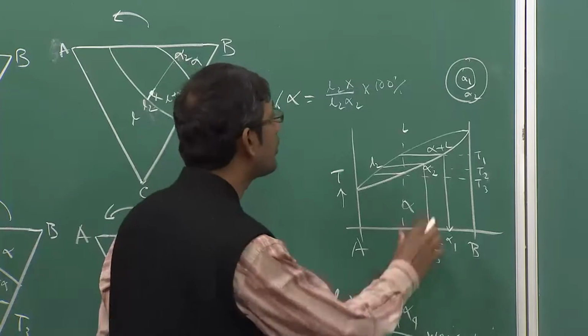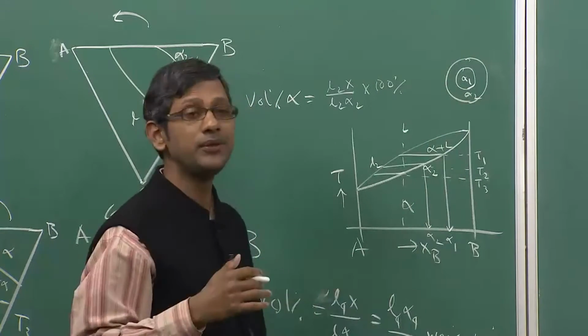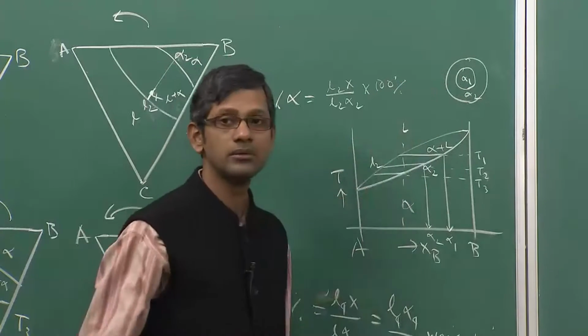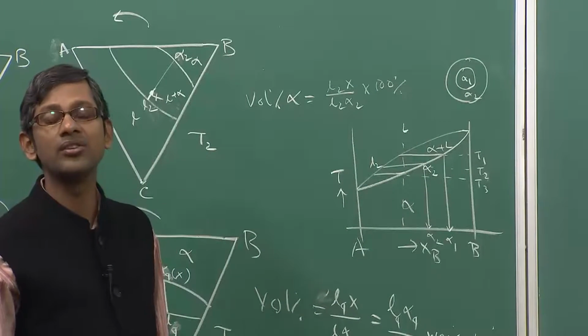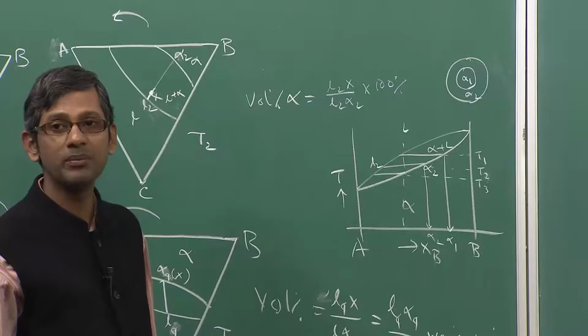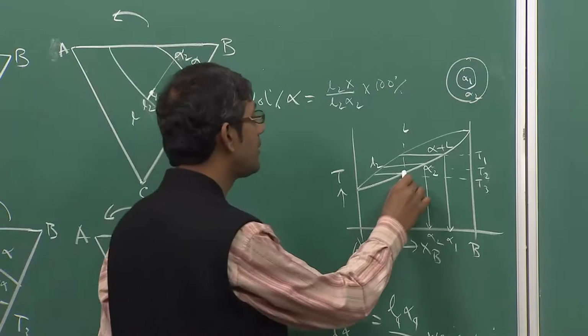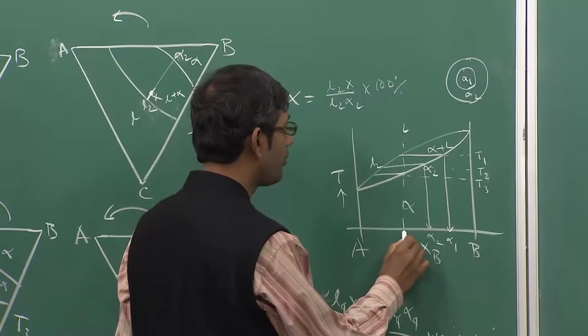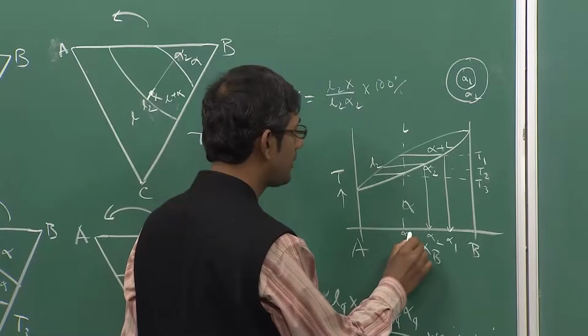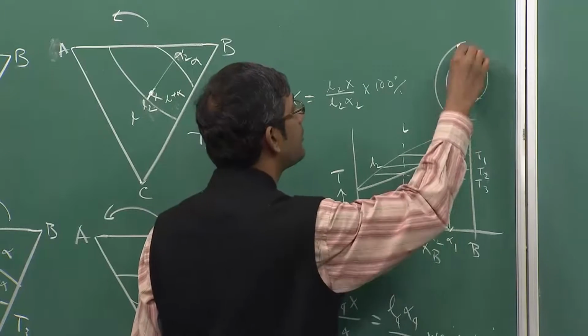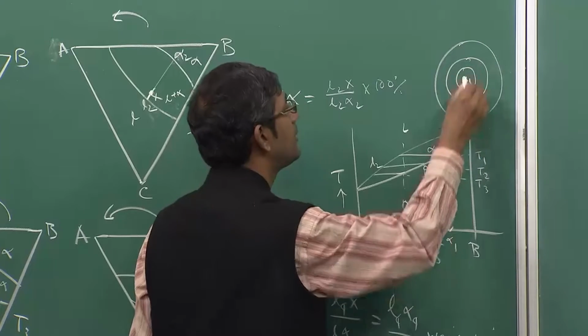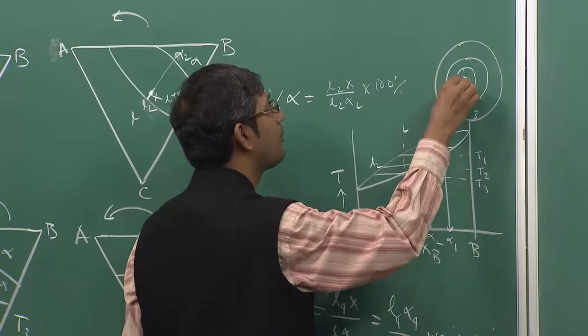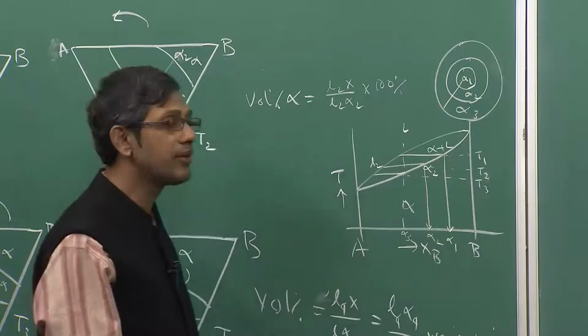Therefore, in order to homogenize them, B has to diffuse from alpha 1 to alpha 2, and this diffusion in solid is not allowed because of the non-equilibrium nature of the processing. So, obviously, the last solid which will form will have a composition given by alpha 3, forming another layer alpha 3. That is the way you are developing a composition gradient from the center to the periphery, and that is what is called coring.